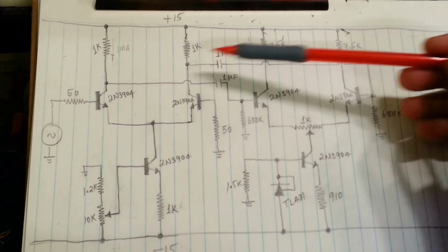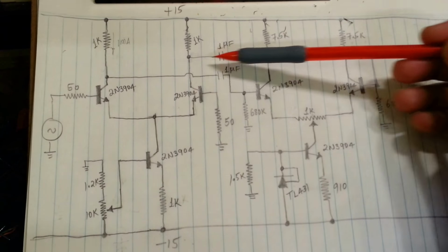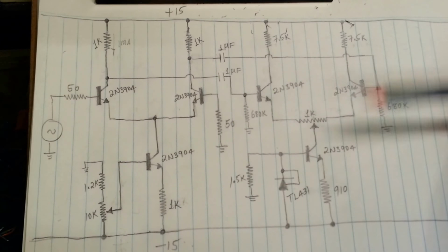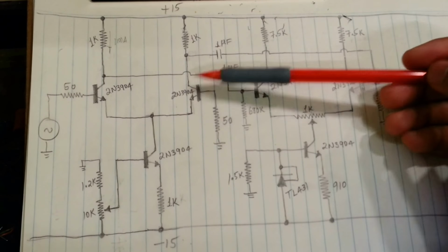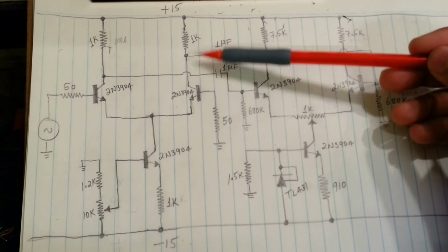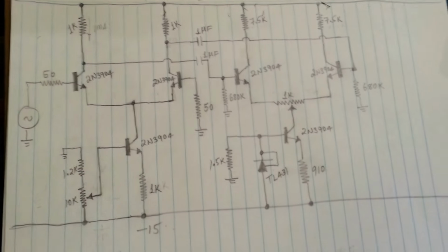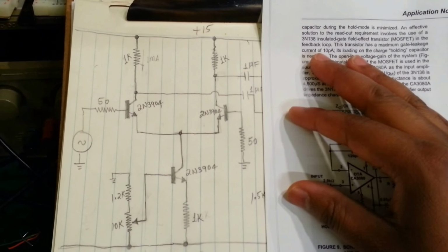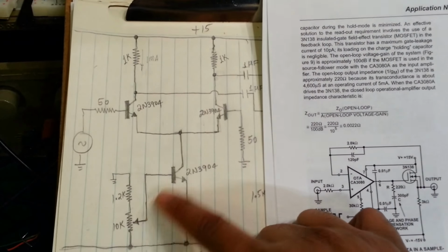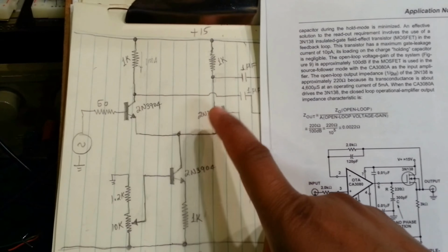because that's the quiescent point shift, and that is cancelled, as you can see, by a second differential amplifier which has a fixed gain, which will remove the quiescent point shift that we have in this stage. So for the moment, let's design this part, which is what we're asked at the moment, which will have a voltage controlled current source here.